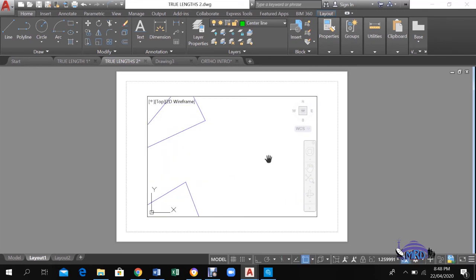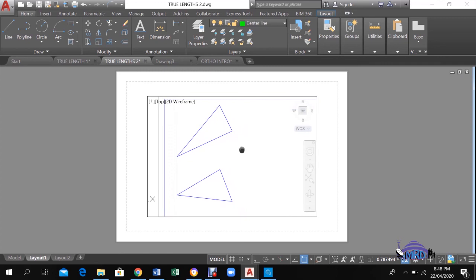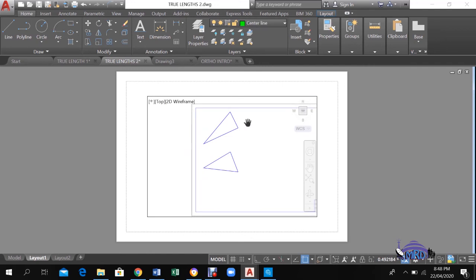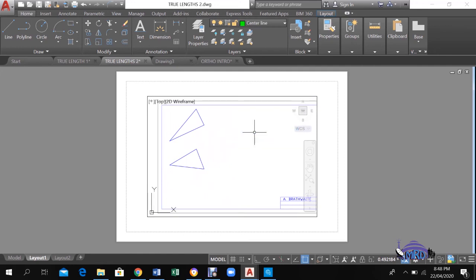triangular shaped lamina. So what we will have on our page is two views of the lamina, and then what we will do is isolate each side, and you know that each side is represented in the front view and plan. We will isolate each side and take that opportunity then to plot the true length for that particular side, and then we will move to another side and then to another side. So just bear that in mind as we go through this construction.